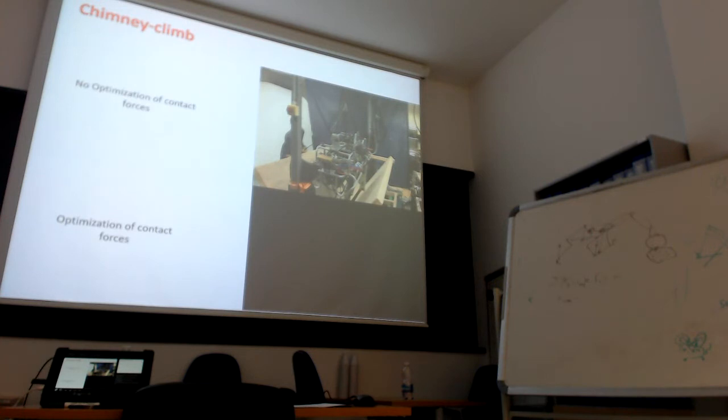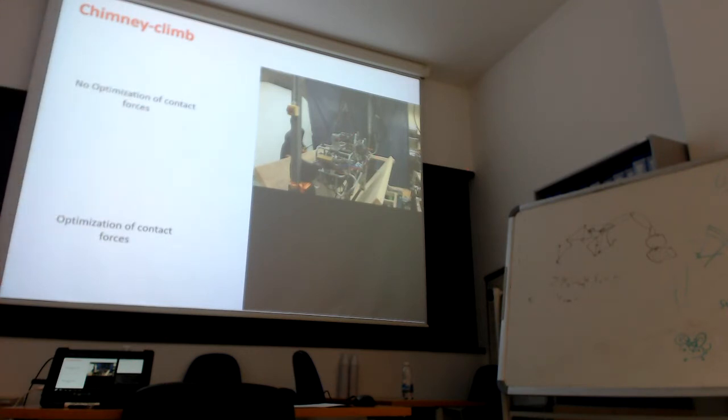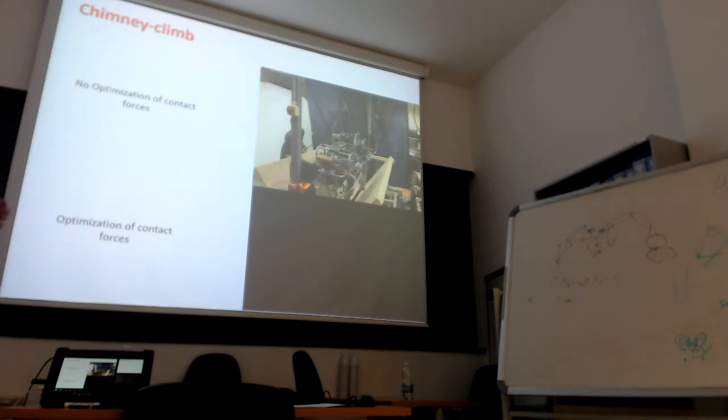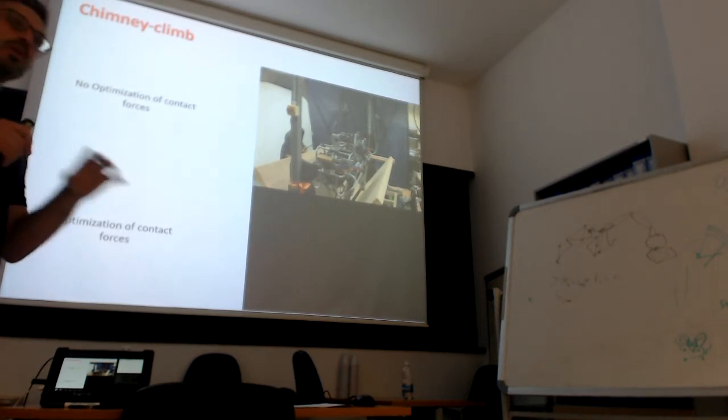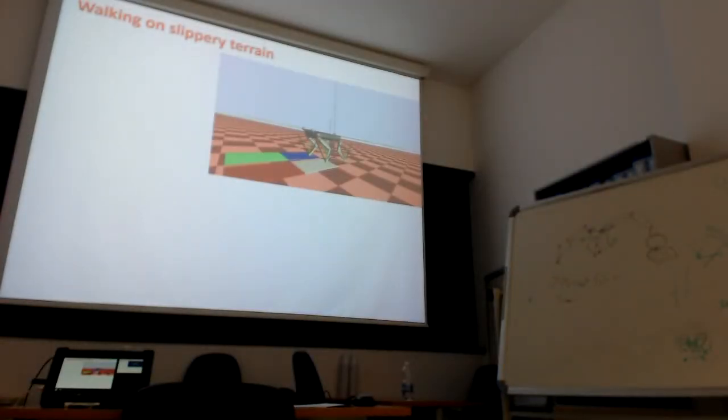Exactly, friction constraint. This was just a constraint in inverse dynamics for this robot without any optimization, and this was a QP problem where we optimize for contact forces and we incorporate friction constraints. So we were able to set the cones normal to the walls and have the forces always inside these cones and avoid slippage. Because for a robot with point feet, the surface is very small, so it's more difficult than for a human to work in such a environment. And the same here.